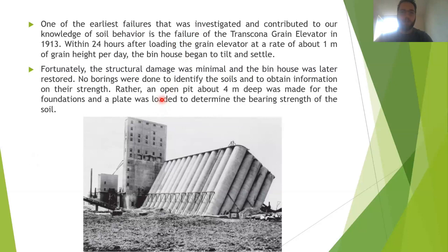Okay. Sorry for not answering in the chat because I was focused on the presentation. So there is no such thing as a poor foundation. There is just poor foundation design. And you need to design your foundation based on the properties of the soil. So this is of course a poor design of the foundations. The thing is that it happened in the previous century, so they didn't have a lot of information about it. But in general, that's why I spoke about the importance of soil investigations.